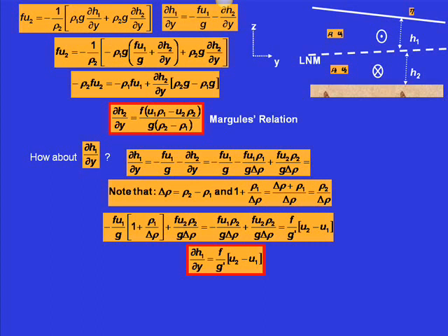That's why it's reduced gravity, the g prime. Probably that has to be part of your morning sayings. So when you wake up every morning and you say square root of g prime H, think about what g prime is also. Remember, g prime is reduced gravity, and it's reduced because you're multiplying gravity times a very small number.